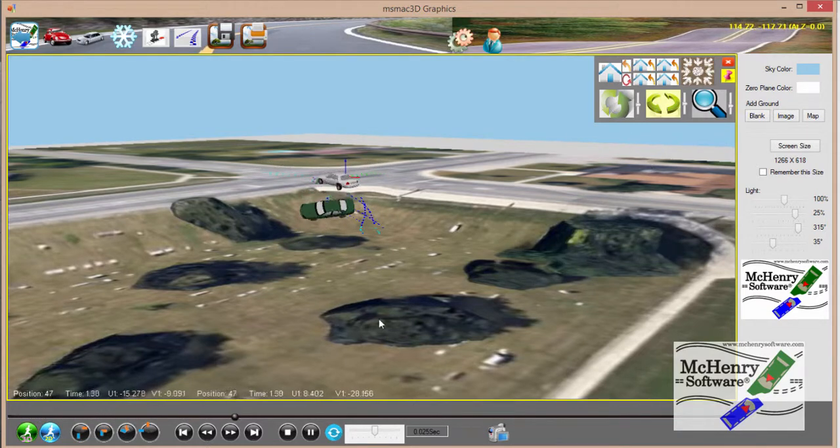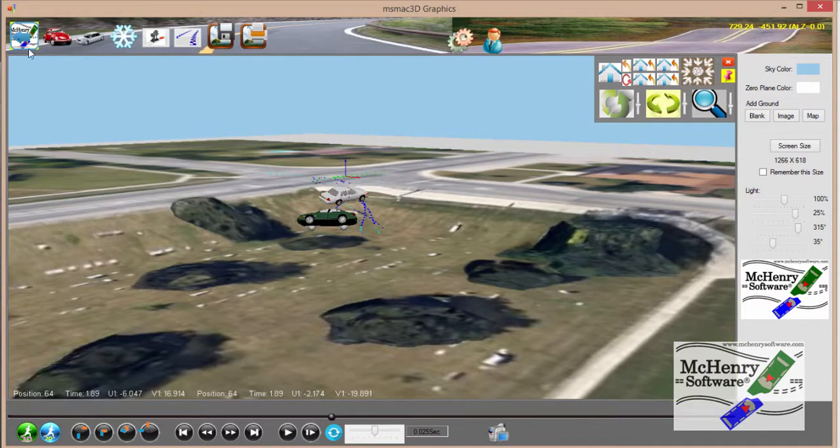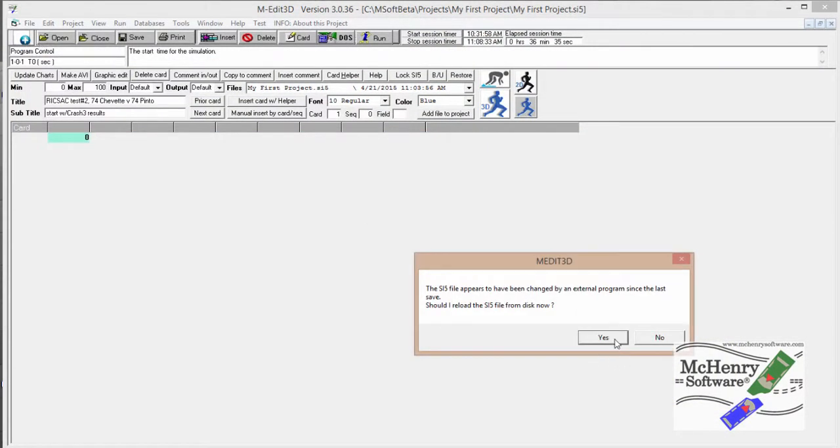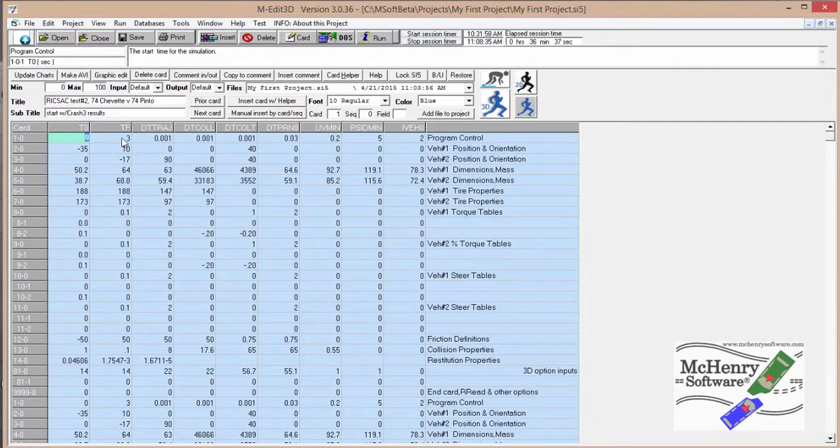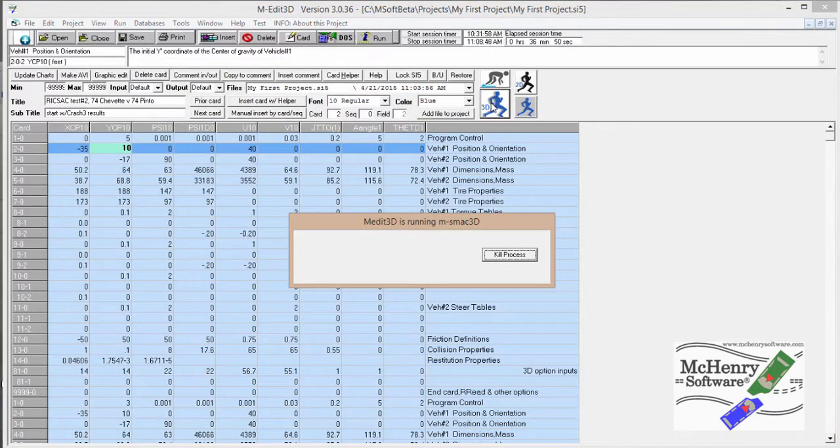Now for one other option, which I'll probably show for the default, to set the time, we're going to have it so it'll be up on the dialog here, but for right now you could just quickly jump back to your SI5 file and set it for 5 seconds. We want to watch it a little longer. Let's just see what we have a friction coefficient of 0.75, which is a little high. We have their CG heights of 22 inches. So then we just click rerun.